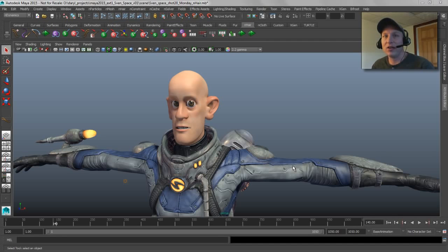Keep in mind that Nhair is great for things other than just hair effects, right? Like you could use it to make ropes or spider webs or a bowl of spaghetti, or you could use it as the physics engine to drive Spline IK down a series of joints. There's actually a bonus tool that sets that up automatically for you for secondary animation on little things. It can also be tied into XGen really efficiently. There's an actual create Nhair button inside of XGen that will make the guides be dynamically driven by an Nhair system. So all the stuff that I'm talking about today with Nhair does have a tie back into the way you would dynamically move hair inside of XGen.